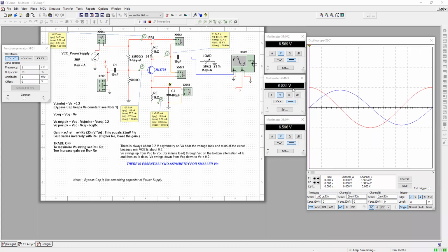Here is where we were before at the 10 nanofarad. Notice that we're looking at something like a 90-degree phase shift. When the blue output peaks, my input is at the starting point or the 0 point. It's actually 90 degrees plus 180 degrees, which we'll talk about later. But you can see the 90-degree delay.